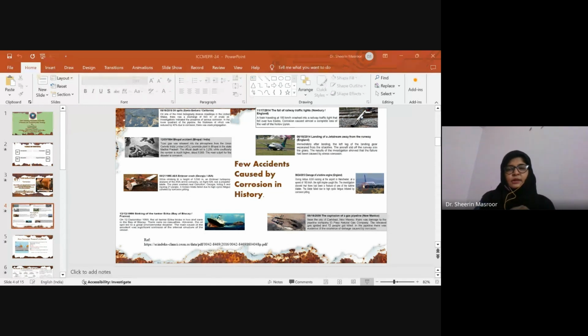Here we are discussing nanocomposite coating. A nanocomposite coating basically consists of two immiscible phases separated by an interface region, and the main components of this coating are the matrix and the reinforcement material. By combining these, we can get a product which is superior in qualities and properties compared to each individual component.